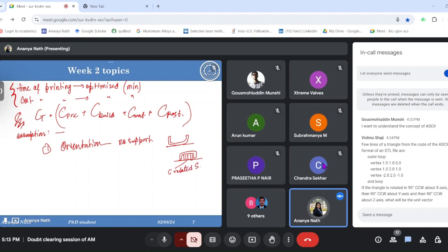The other thing is, when you remove the support, this surface will not be as good as the surface which is built without support. Wherever you remove the support structure, that surface gets rough, unlike the other surfaces of the printed part. That's why we sometimes try to avoid putting any support structures.